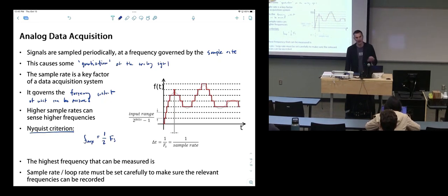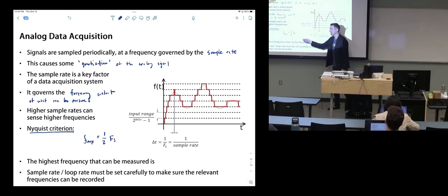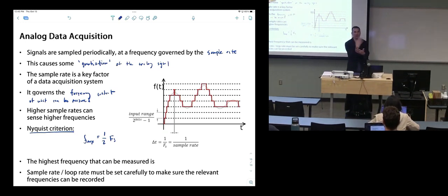I'm actually not going to talk about aliasing in depth, because I didn't want to go any further into this. But for aliasing, let's say we're sampling at 100 hertz. We have a 50 hertz Nyquist frequency, so we're not going to be able to read anything faster than that. And we know there's a 200 hertz sine wave in that signal. That's much faster than we can see.